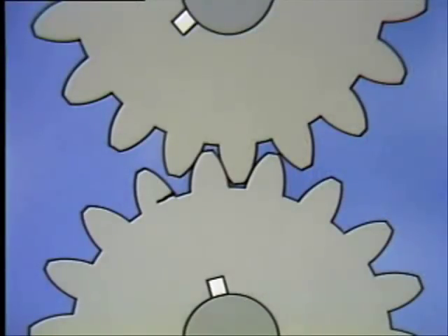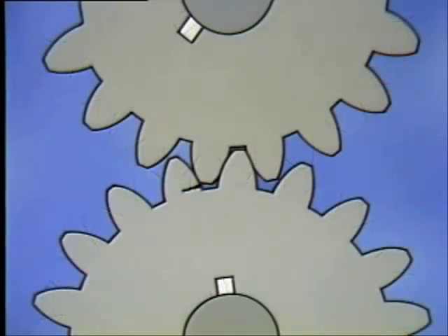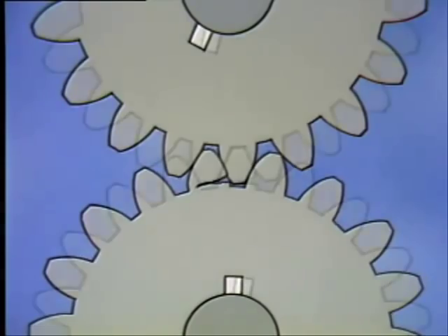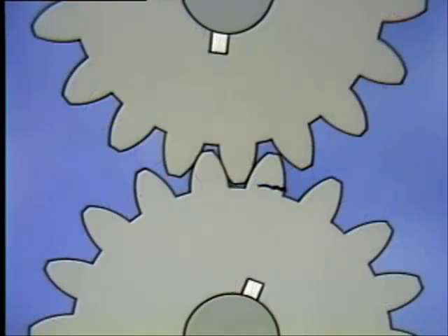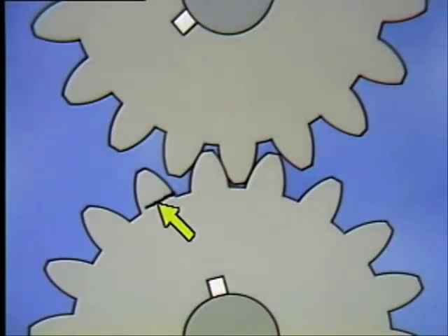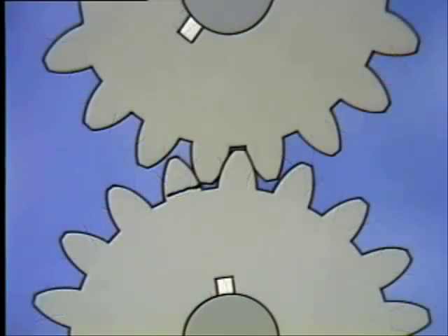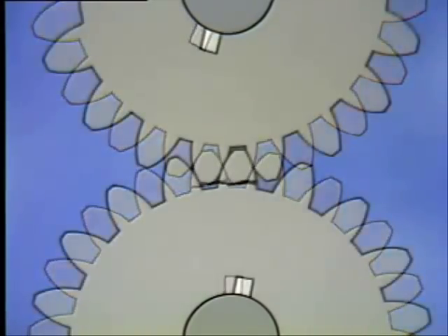The process of fatigue failure will be accelerated if some defect was present when the gear was manufactured, such as a tiny crack in the gear material. As the gear tooth passes through its mesh, the tooth is loaded and then unloaded. This loading and unloading process will cause the original defect to increase in size. And eventually, the defect will grow large enough that the gear tooth will break.